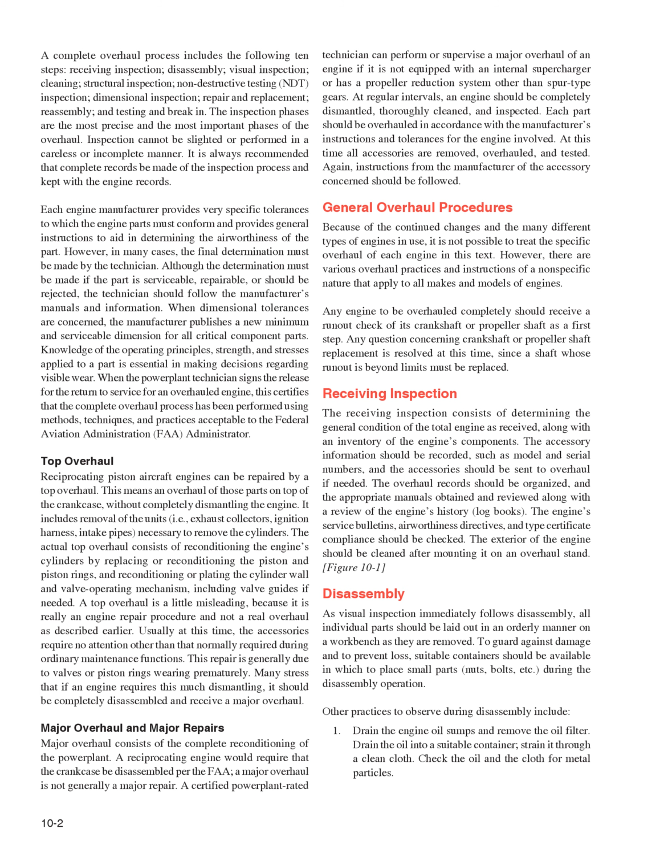Although the determination must be made if the part is serviceable, repairable, or should be rejected, the technician should follow the manufacturer's manuals and information. When dimensional tolerances are concerned, the manufacturer publishes a new minimum and serviceable dimension for all critical component parts. Knowledge of the operating principles, strength, and stresses applied to a part is essential in making decisions regarding visible wear. When the power plant technician signs the release for the return to service for an overhauled engine, this certifies that the complete overhaul process has been performed using methods, techniques, and practices acceptable to the Federal Aviation Administration, FAA administrator.